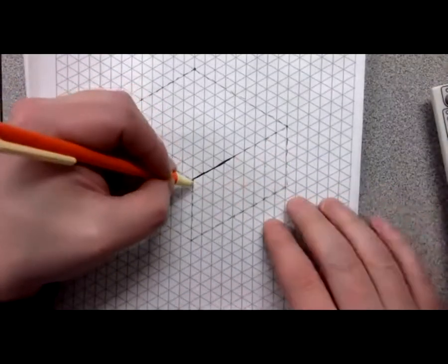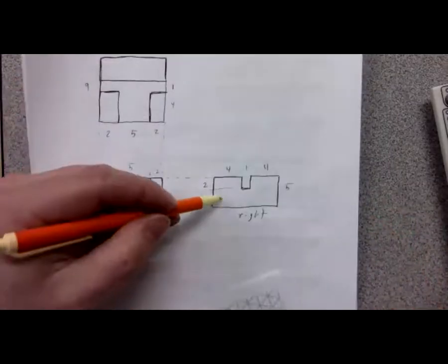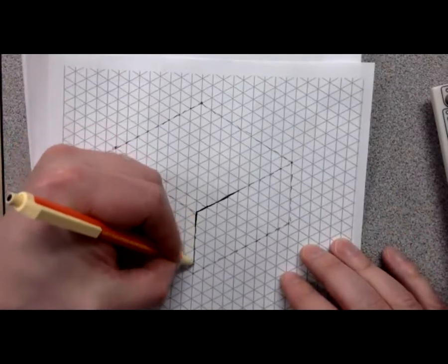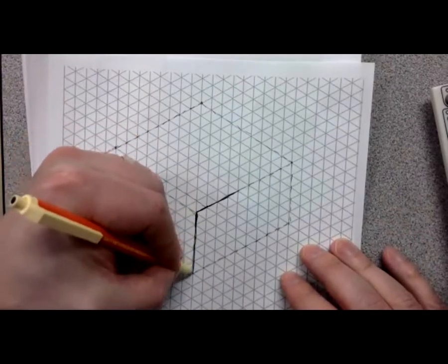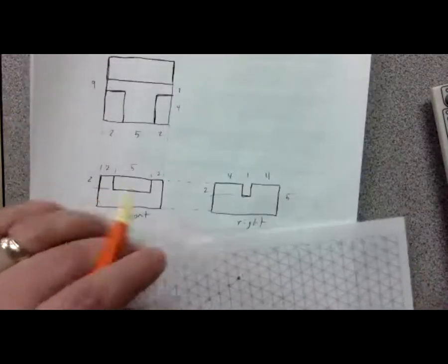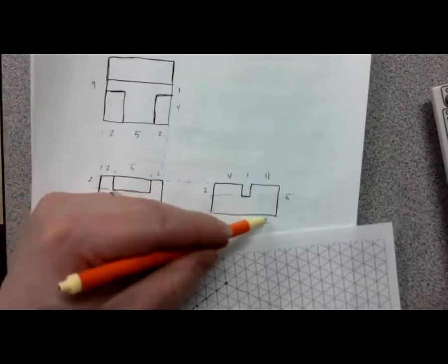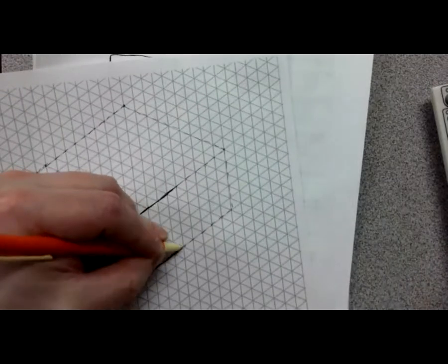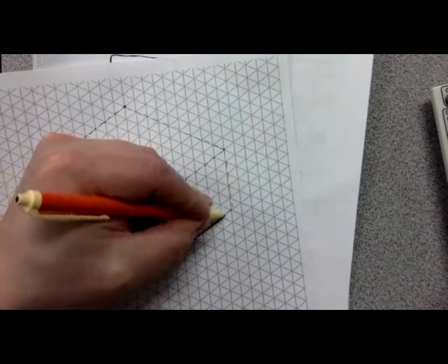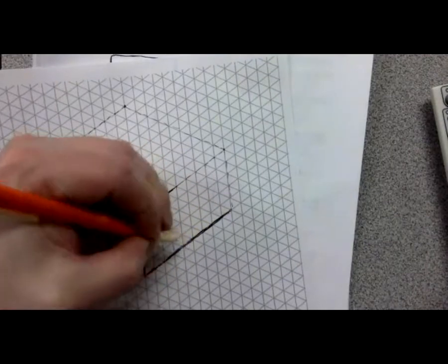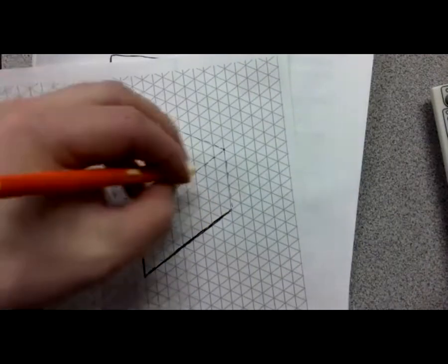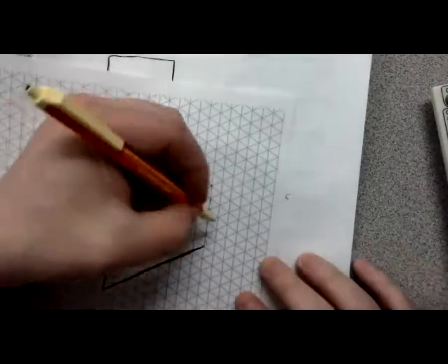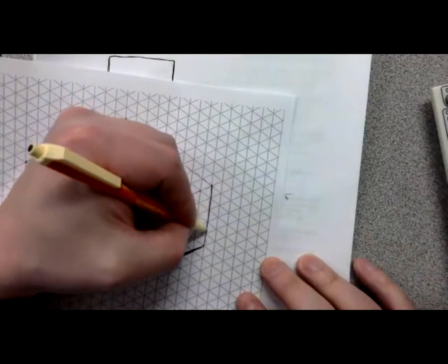I see this right face as being right at me because there's only one face on the right. That means it's probably right here at me. So this vertical line here is solid. This line here on the bottom is completely solid, 9 long, solid on the bottom, on the right projection. So this line right here is a solid 9 long line. And this other edge over here, that's the vertical, so I'm going to have 5 vertical solid right here.